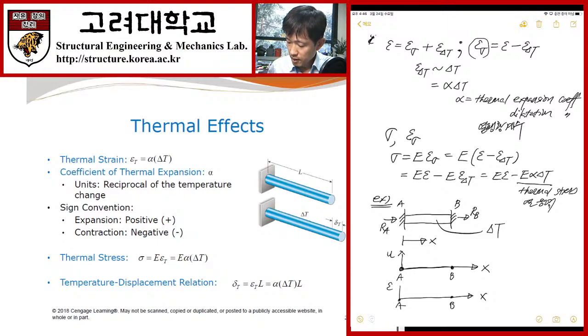Alright, now because I have the strain, using this formula I can calculate the stress field. My stress is equal to elastic modulus times, as you note here, my strain is equal to 0 in this member, so 0 minus the thermal strain. The thermal strain is alpha delta T, so the stress is equal to minus E alpha delta T. Is it clear, right?